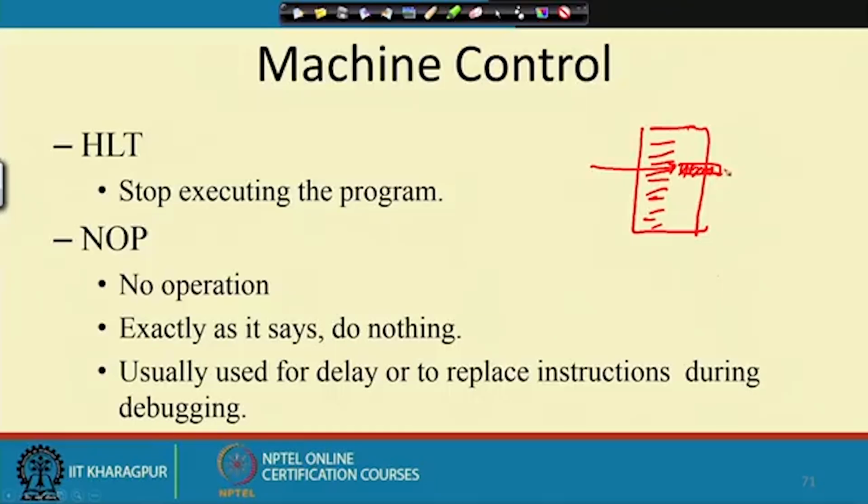Now, you have incorporated these instructions into the program, and this is done at the time of compiling or assembling the program itself. Later on, when the program is working properly, what to do with these instructions? If you want to remove these instructions, you need to reassemble the program by removing all those places. So, a better option is needed, because later on you may also need this debugging.